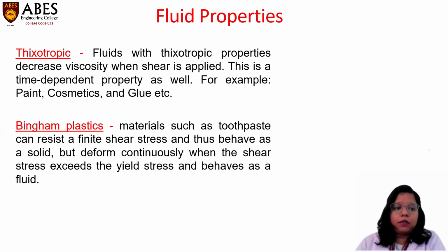The other one is Bingham plastics. What are these? Materials such as toothpaste can resist a finite shear stress and thus behave as a solid, but they deform continuously when the shear stress exceeds the yield stress and behave as a fluid. These are the properties of non-Newtonian fluids.